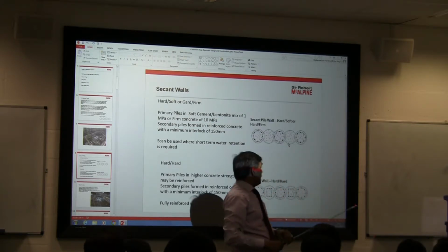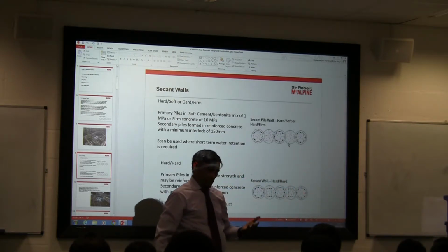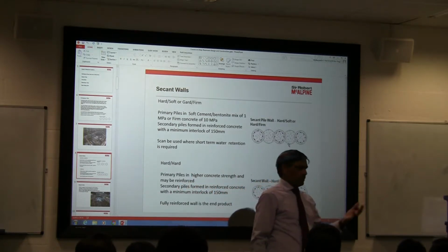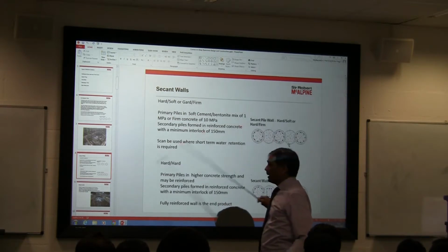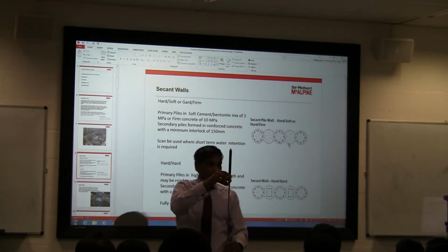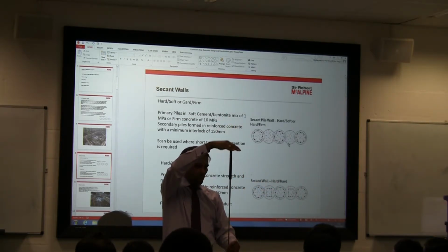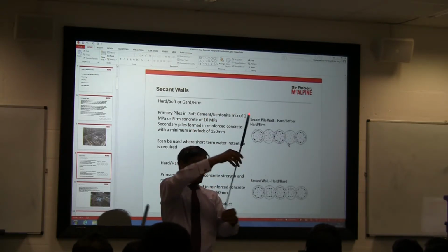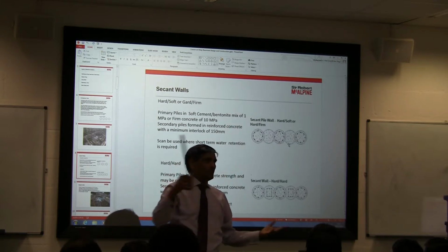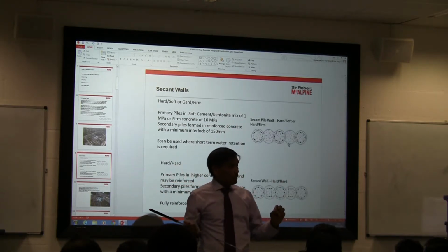So we want to make sure at every depth, especially deep piles, if you go for 4 meters, 12 meters, 20 meters, whatever, by the time you go to 20 meters that pile is supposed to be vertical. It will be, but because you are driving from here, it may end up like that. And then when you do the next one, that may end up like this. And you do the middle pile, there is no interlock, is there? So we want to make sure of the tolerance control.